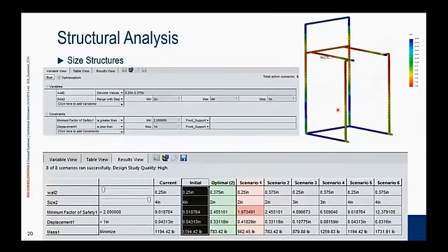The second facet of this is then finding what sized weldment we need to carry that load. And this is where design studies really are a huge benefit, and they're very easy to set up. We're just modifying or driving the dimension for the weldment tube size, and it's just a matter of picking that dimension on the screen. It gets plugged in here, specifying the range. In this case, we're just doing 2 inch, 3 inch, and 4 inch size weldments with wall thicknesses of 1/4